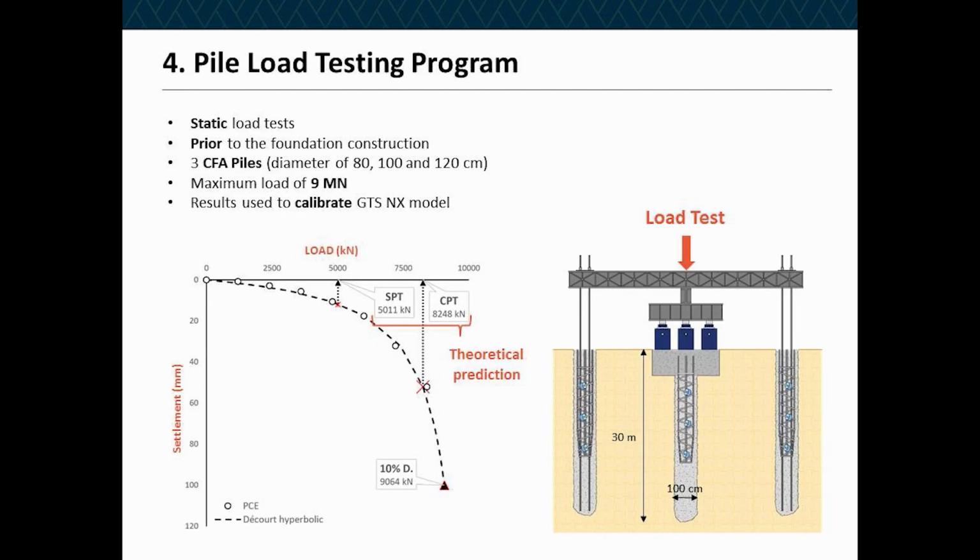So here we are heading to the pile load testing program. The static pile load test, just to define it, is composed of a real scale pile, which is tested by applying loads, and at the same time the settlements are recorded for each load step. The figure on the right shows the test scheme, which is basically composed of the test pile and the reaction piles.